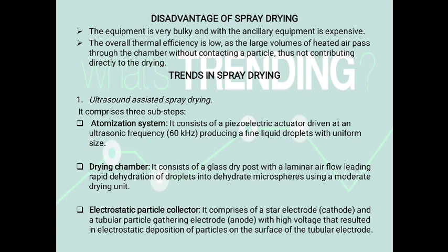Here are the trends in spray drying. Number 1 is ultrasound assisted spray drying. It comprises 3 sub-steps. The first one is the atomization system. It consists of a piezoelectric actuator driven at an ultrasonic frequency of 60 kHz, producing fine liquid droplets with uniform size. The second is the drying chamber.